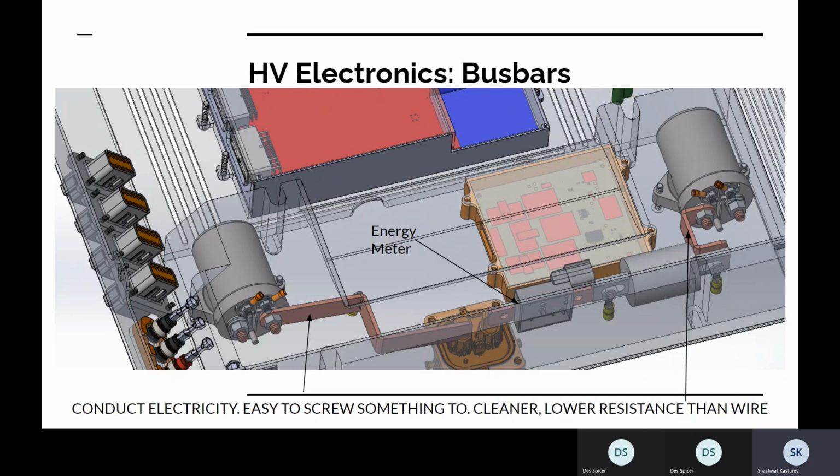Okay, yeah. I explained the benefits of bus bars. You can get into tighter spaces with them because the bend radius of zero gauge cable is massive, right? Bus bars you just bend to 90 degrees, 45 degrees, whatever you want. They're also low resistance. That's a key thing.